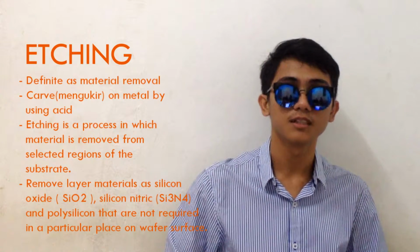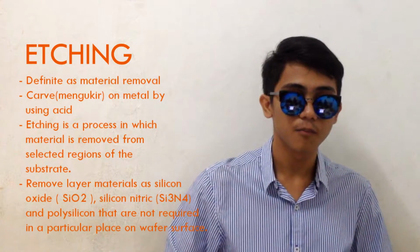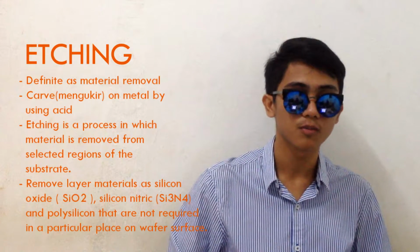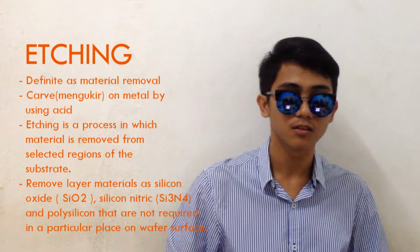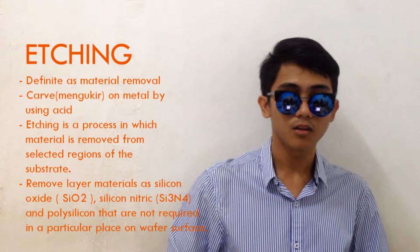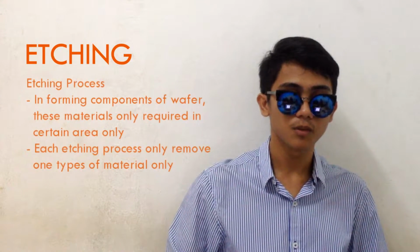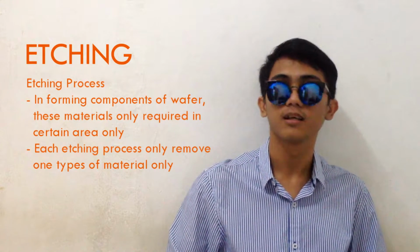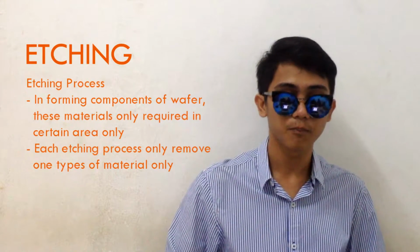Next, about the etching process. Definition: material removal, carving metal using acid. Etching is a process in which material is removed from selected regions of the substrate. It removes layer materials such as silicon oxide, silicon nitride, and polysilicon that are not required in particular places on the wafer surface. These materials are only required in certain areas only. Each etching process only removes one type of material.